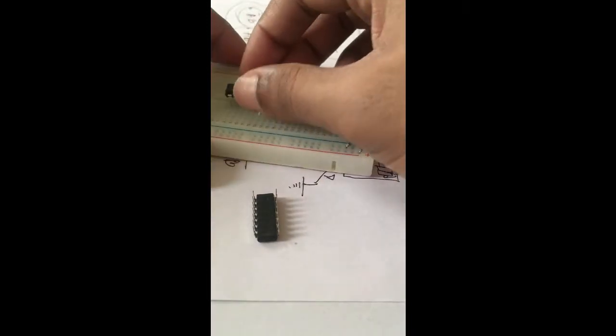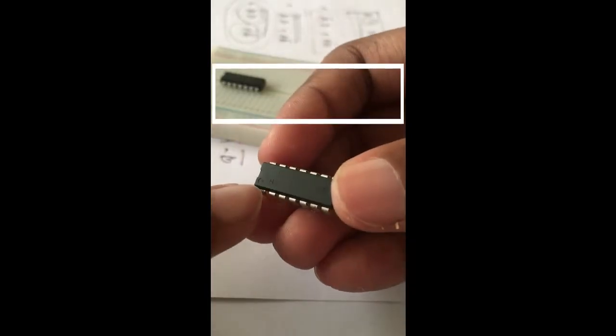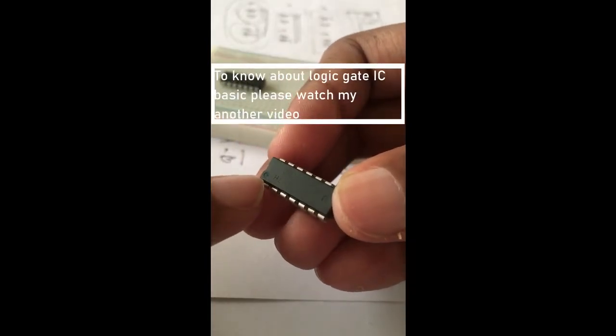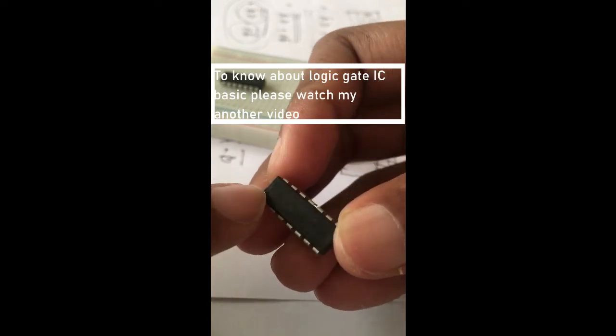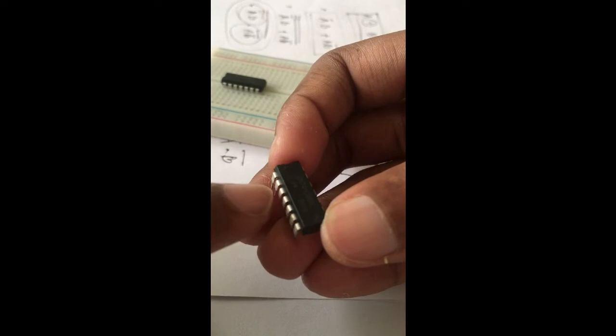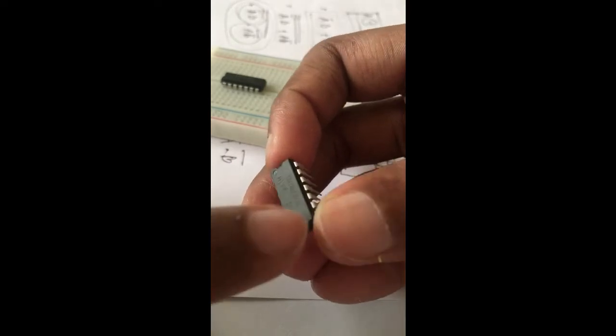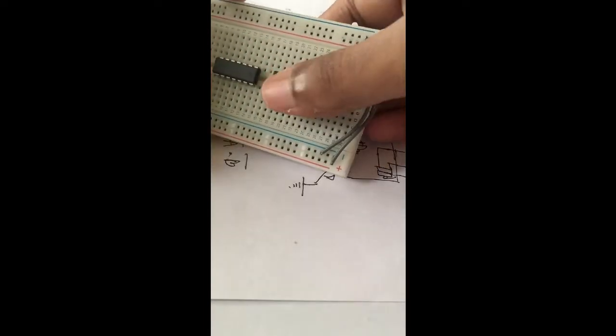Here I put the IC. This round circle indicates pin number 1. You can see a curved mark in front of this IC, and it starts from here: 1, 2, 3, 4, 5, 6, 7, 8, 9, 10, 11, 12, 13, 14. Pin 14 is for power, so we have to power both of the ICs.